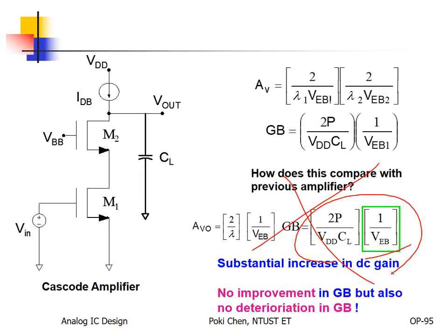All right. Anyway, I told you already. If you would like to enhance ro, then the bandwidth will be reduced. So no gain in gain bandwidth product. I warn you again and again. That is only one. If you would like to enhance gain bandwidth product, you need to focus on this.